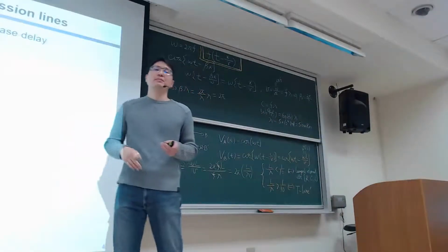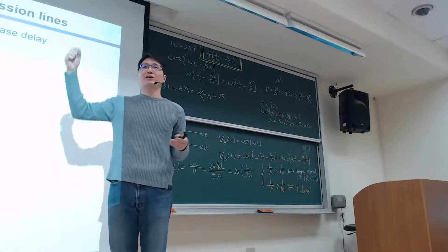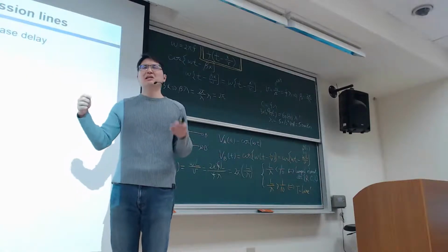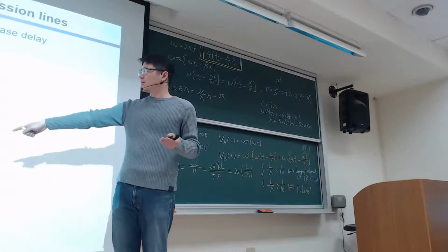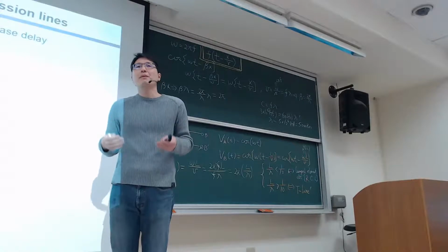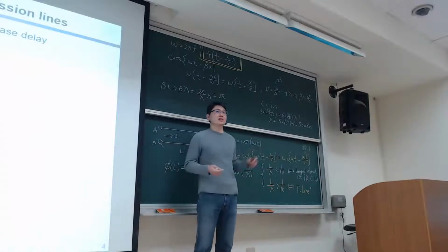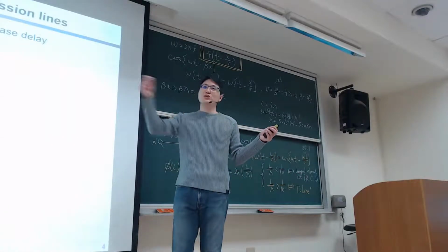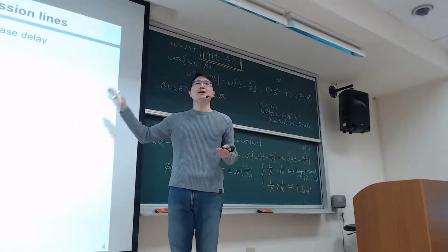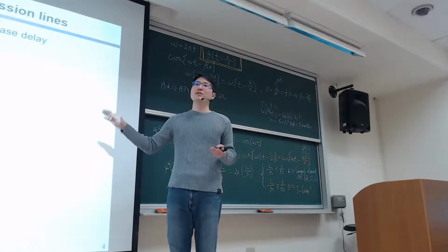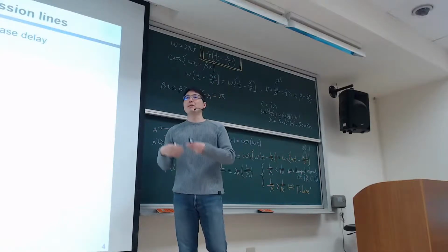When using the power line, the wavelength is 5,000 kilometers, but the entire length of Taiwan from Keelung to Kending is roughly 400 kilometers. So you don't really care. All the metallic lines connected in Taiwan could probably be viewed as just lumped elements, right? Under this assumption. But in the United States, from Los Angeles to New York is about 5,000 kilometers. So in that case, the same two wires need to be viewed as a transmission line. You will see phase dependence. You will have wave propagation behaviors.